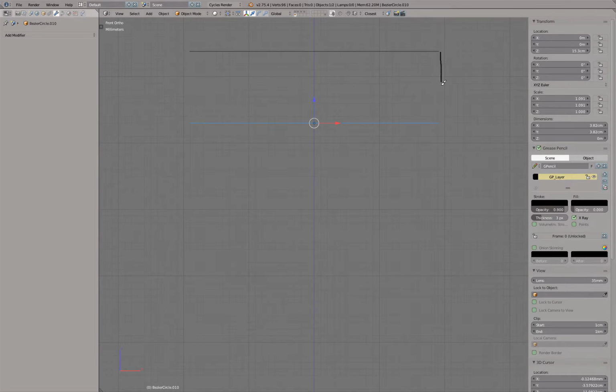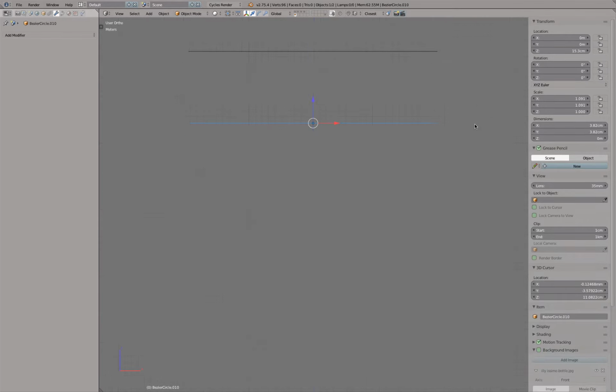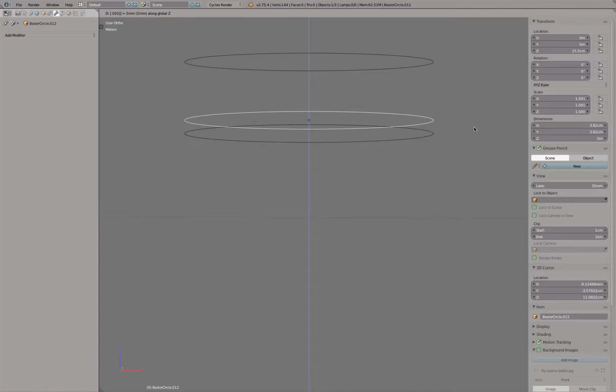Design-wise, there's a line that comes down and then at one point it bevels out slightly. So we have to build this part where the metal is folded into a rounded shape. We have an upper edge that is 2.3 millimeters high. So what we can do now is press Shift D, Z, .0023. Let's make it 2.5 for easier steps and press enter. Okay, perfect.